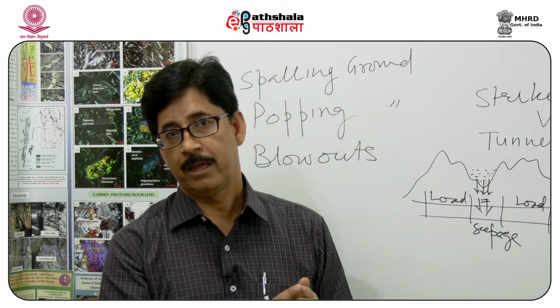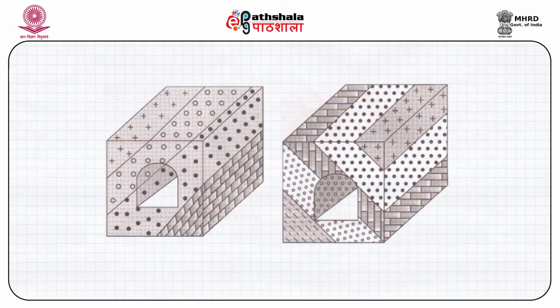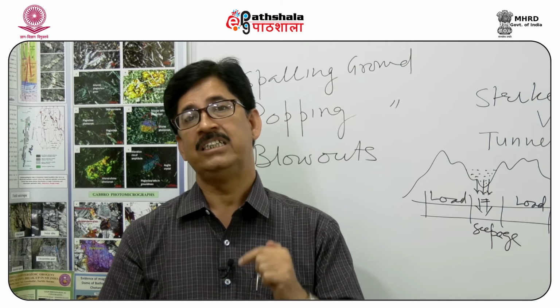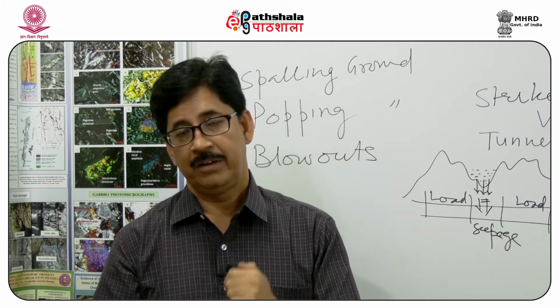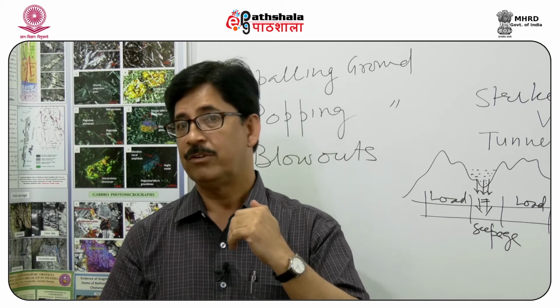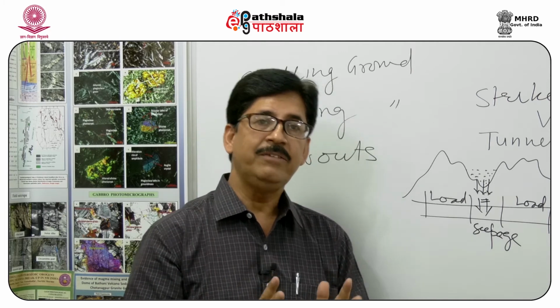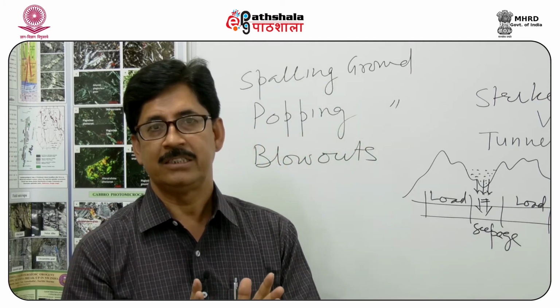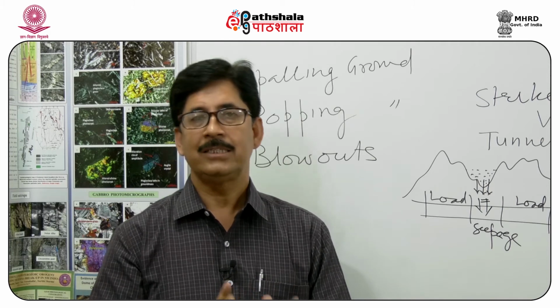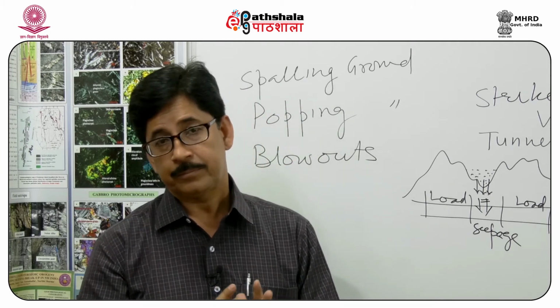horizontal rocks. If you have rocks dipping towards you, then the tunnel excavation is termed as drive against the dip. If the rocks are dipping away from you and you are excavating for tunnels, then it is called as drive with the dip. The drive against the dip is difficult and dangerous as compared to tunnel drive with the dip.